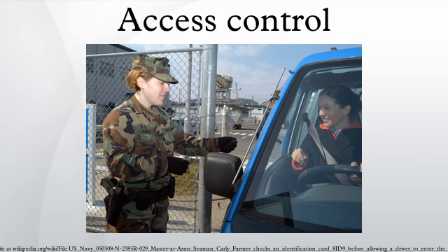Disadvantages: the system becomes susceptible to network-related problems, such as delays in case of heavy traffic and network equipment failures. Access controllers and workstations may become accessible to hackers if the network of the organization is not well protected. This threat may be eliminated by physically separating the access control network from the network of the organization. Also, it should be noted that most IP controllers utilize either Linux platform or proprietary operating systems, which makes them more difficult to hack. Industry standard data encryption is also used. Maximum distance from a hub or a switch to the controller is 100 meters.